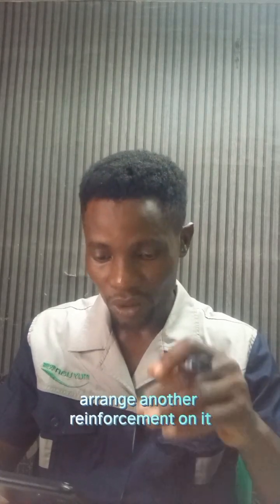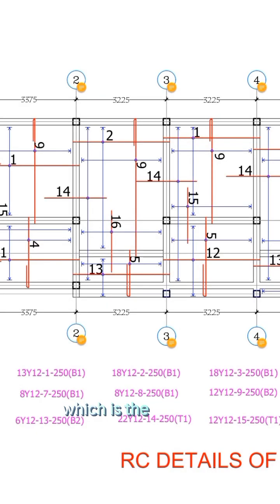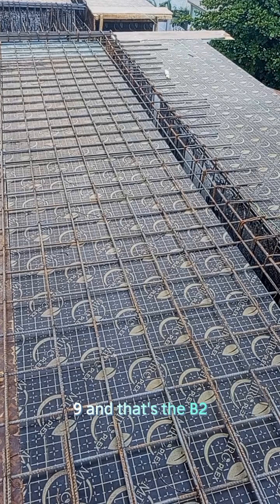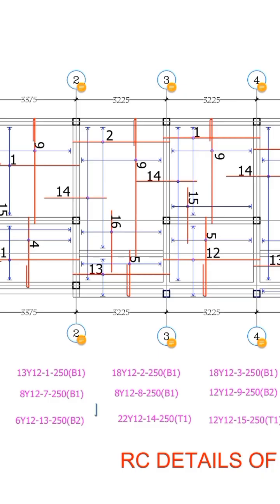After that, you need to arrange another reinforcement on it, which is the one I labeled 9. Now that's the B2. You call it the bottom top. That is the B2. In the callout, I labeled it as 12 numbers of 12 mm reinforcement. The bar mark is 9. The spacing is 250, and it is the B2. That is bottom top reinforcement.